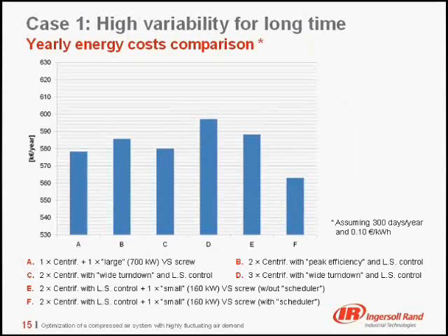The centrifugal type or the variable speed screw? The solution C has not this problem because the 2 centrifugal compressors are exactly the same. So the third compressor would be equal to the other 2 using the same spare parts.